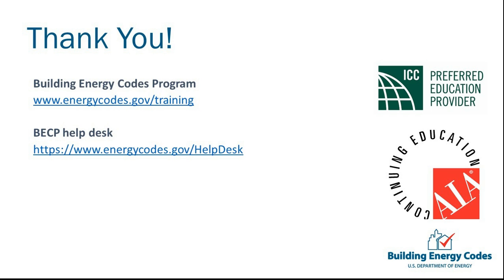Yeah, and I'll just add that, for those who aren't familiar with the 2021 version of IECC and weren't part of the hearings, what Mike was talking about, the prior versions of the IECC had this additional efficiency measures where you picked one. So it might be high efficiency lighting, or it might be higher efficiency mechanical equipment. It was like you just picked one off the list. For the 2021 IECC, there was a proposal that turned that into a point system, recognizing that U-factor is more important where I live in Wisconsin than it is in Florida. But cooling is very important in Florida. So it gives relative points based on what feature you're doing, and you have to earn a certain number of points.